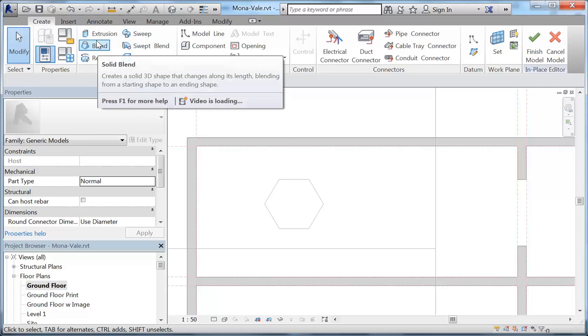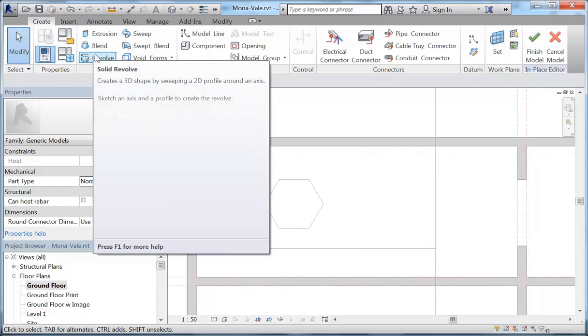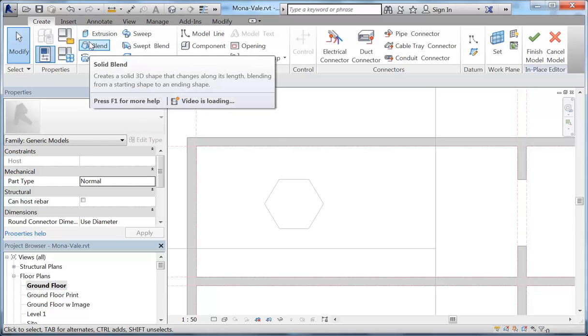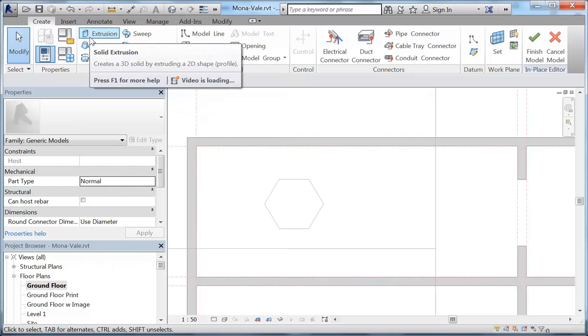Okay, so we choose the model thing, we select what we want to do, we rename it, or whatever. Then, this is where I get lost, do we extrude or do we use model lines to get the... Yeah, you do extrusion. So you need to be in your section view and then making an extrusion. No, definitely don't want model lines.